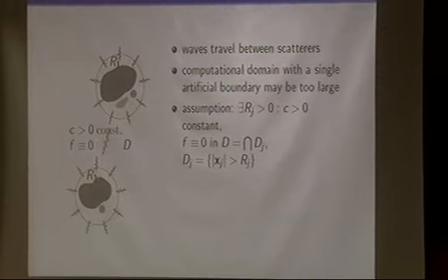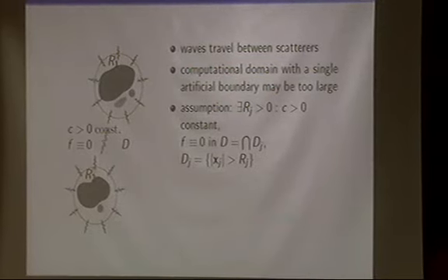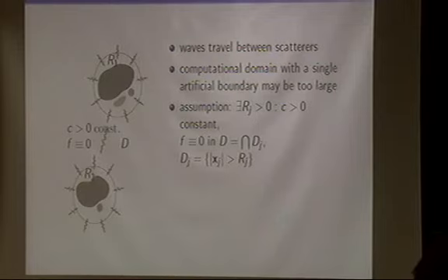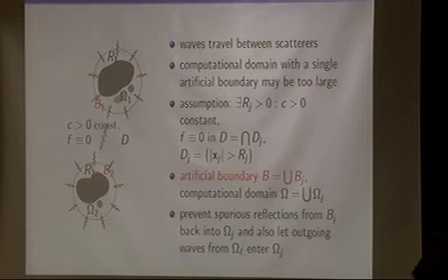The problem is that if you calculate this one, the wave propagates from here to here and here. So during your calculation, you always have the interactive waves, right? You have to capture this one also. So we need a new type of boundary conditions. In PML layers, we absorb the waves. The problem is if the waves are absorbed in the PML layer, we don't know exactly what happens in another direction, right? But if you use other boundary conditions, you can perhaps capture these outgoing solutions.